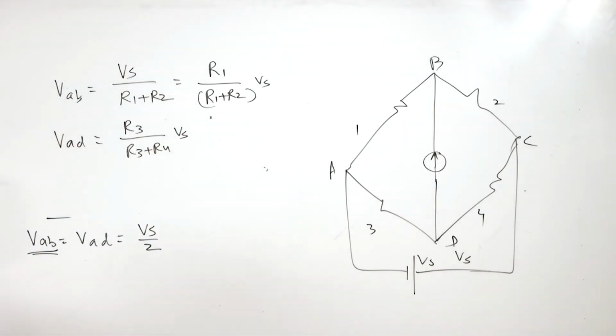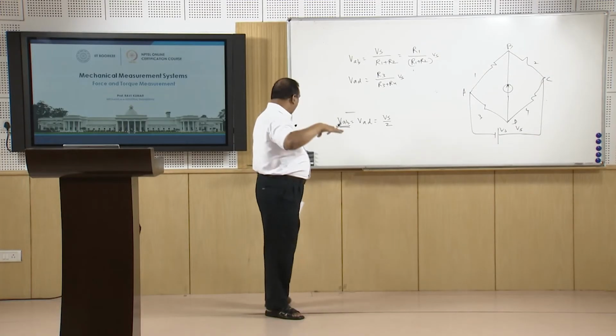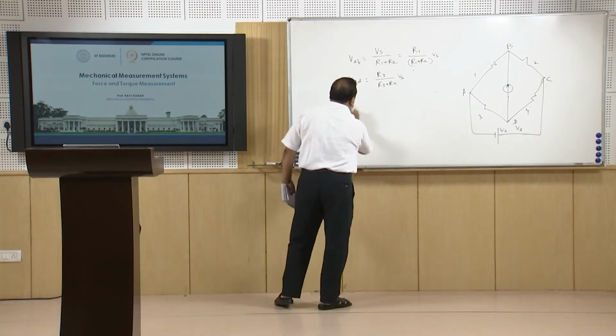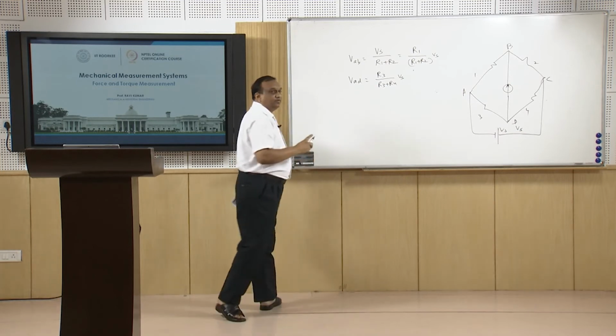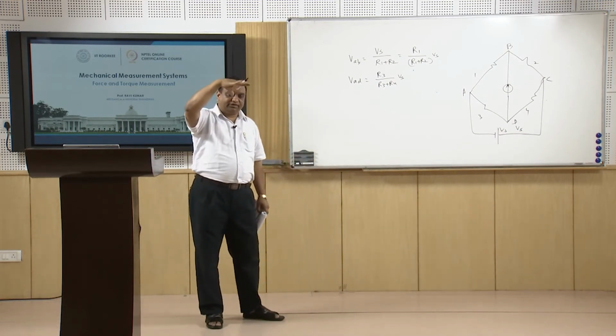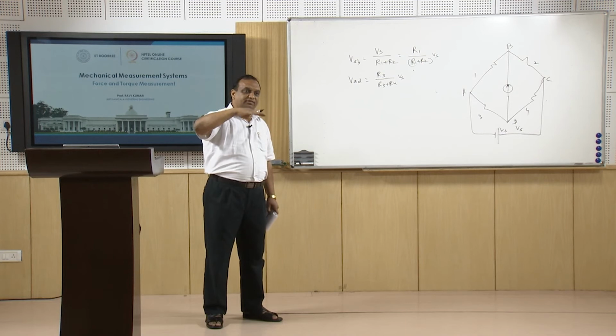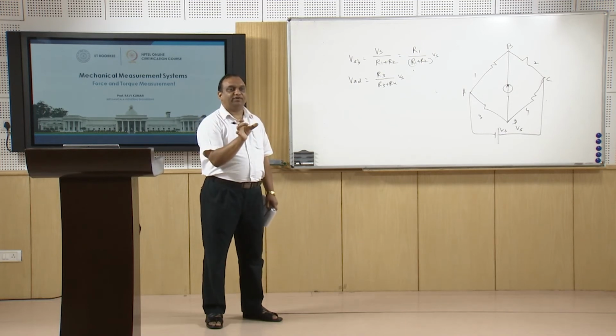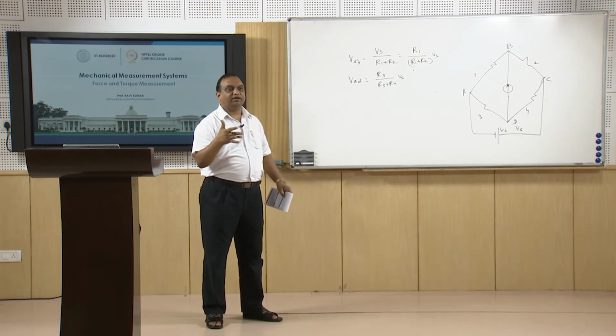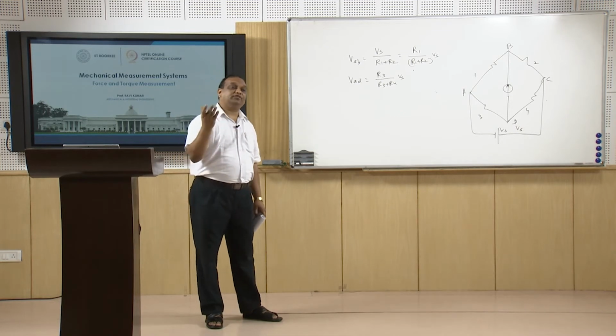Right? Now, the vertical column is put under force. When it is put under force, the strain gauges which are along the axis will be compressed, and the strain gauges which are on the diameter, perpendicular to the axis, because the diameter will increase, will come under tension, or vice versa.